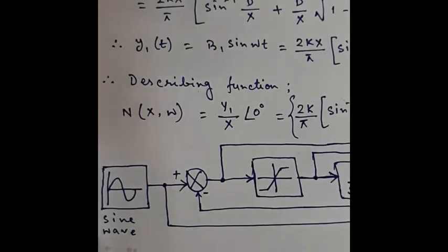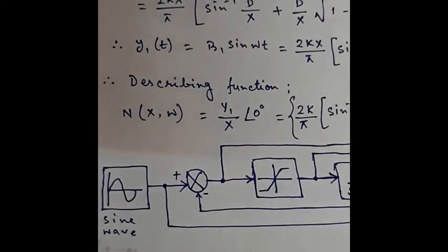To find out the nature of the system, if we introduce the saturation nonlinearity to a plant, we can easily observe it using MATLAB software. In MATLAB Simulink, we have to draw a block diagram. In the block diagram, we take some basic blocks such as the source. For this case, we consider a sinusoidal wave as the source or supply. Then there is a summing block, a two channel summing block. Then this is the nonlinear block, the saturation nonlinear block.